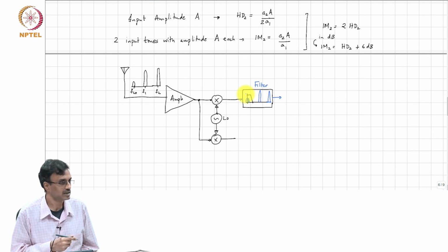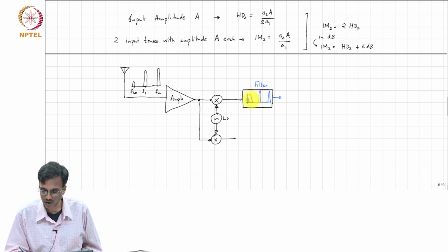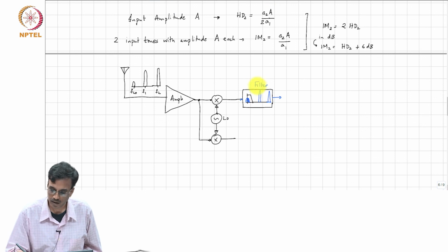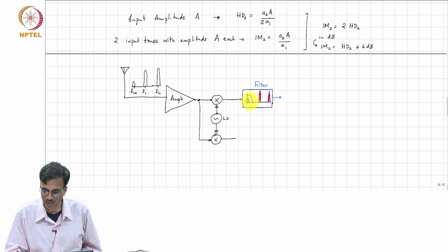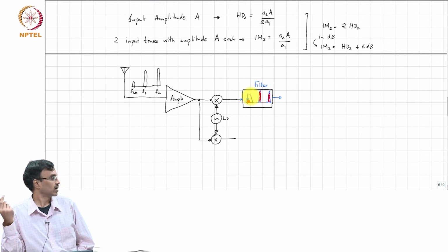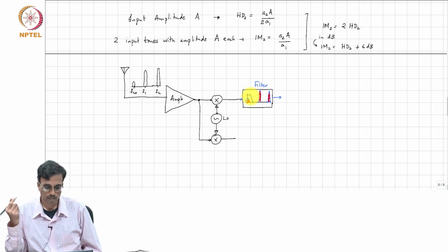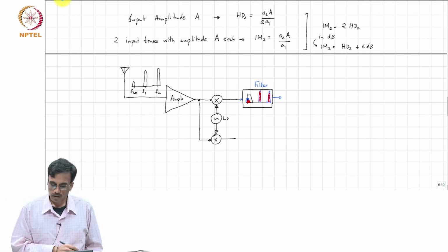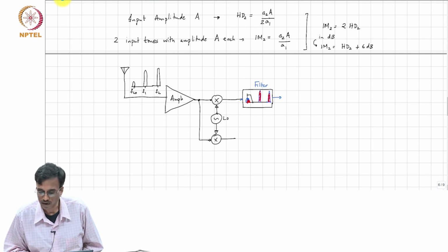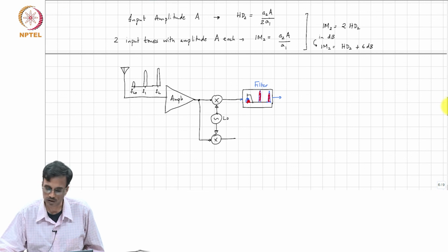You do your best to make them as linear as possible, but if you have two large signals, these two will, through IM2, cause, if they are two very closely spaced tones, something here which can be confused with your desired signal. That is what you need to be aware of with regard to second order distortion.